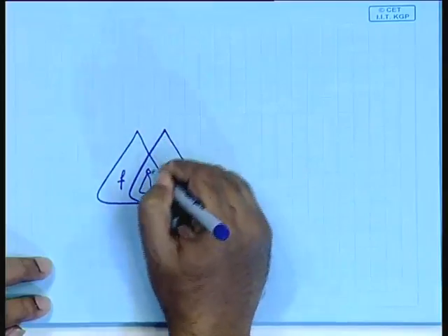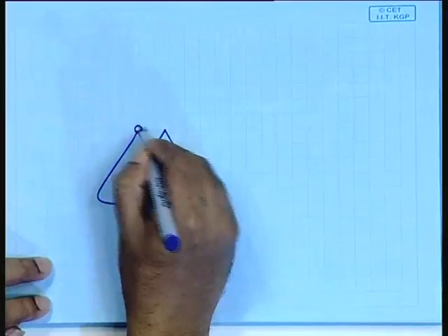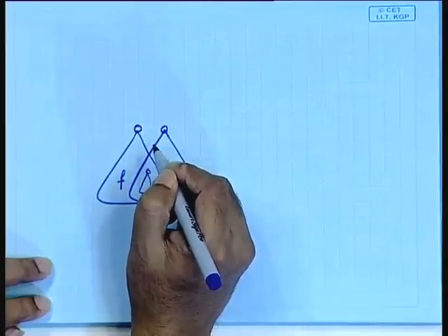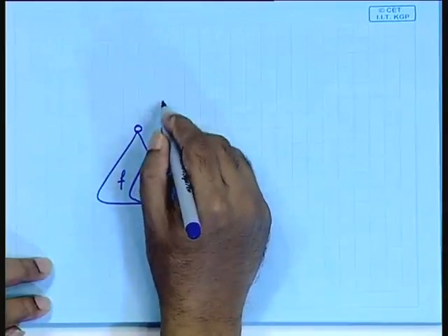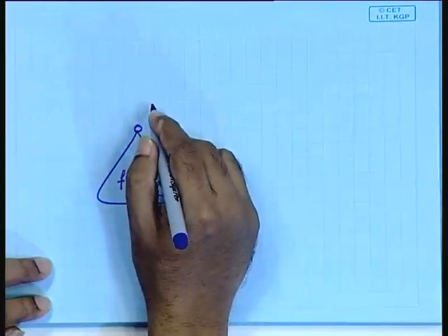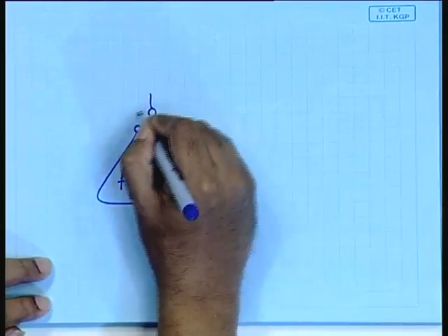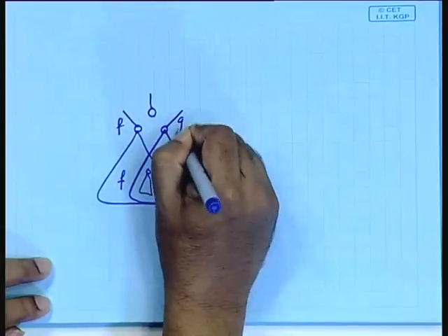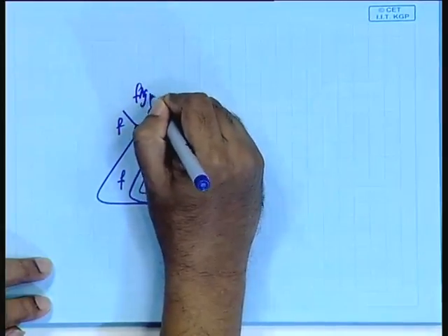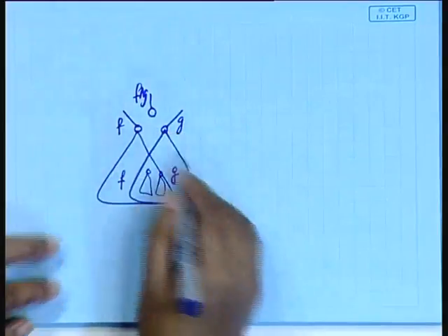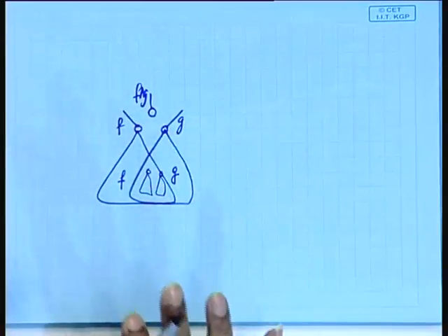These are part of f, these are part of g, and then when you do f and g, okay, it is going to build the f and g using these and return you some node. So, this was your f, this was your g, it is going to give you some node corresponding to f and g, but these are also there in the same thing. So, you have a notion of a BDD manager. The BDD manager is the data structure for this whole thing, and then for each of these BDD functions you can have one BDD, right.